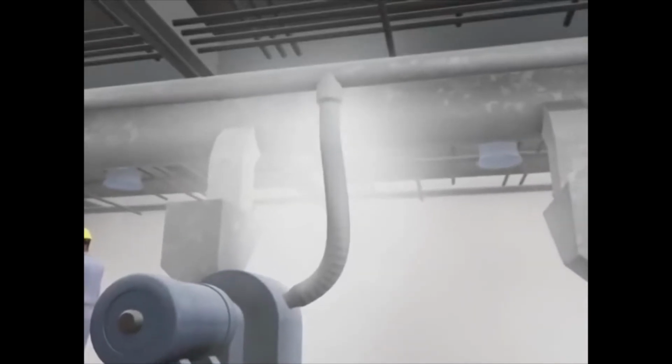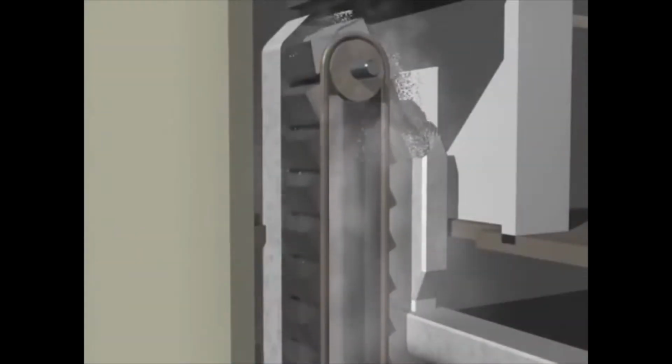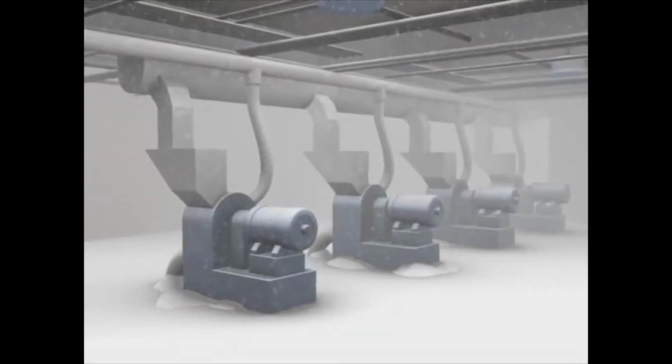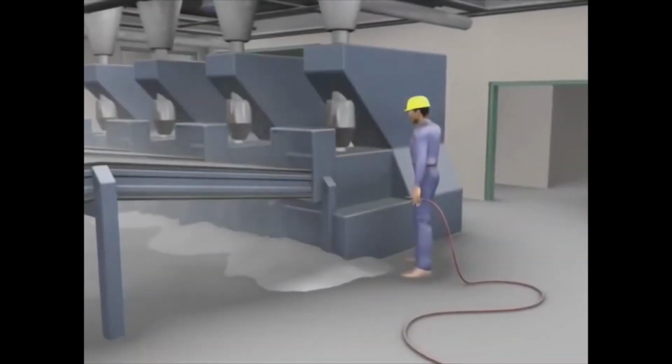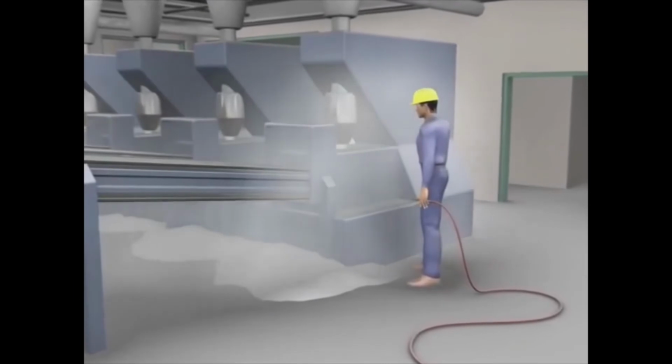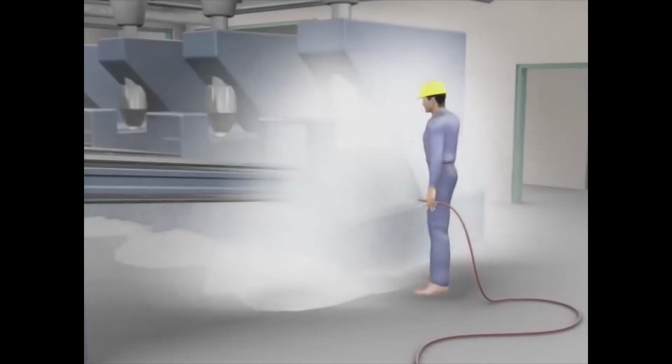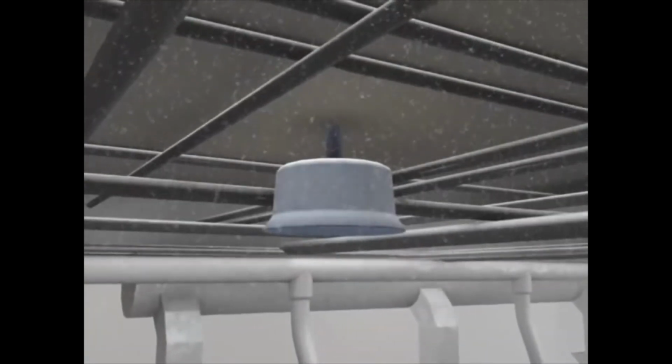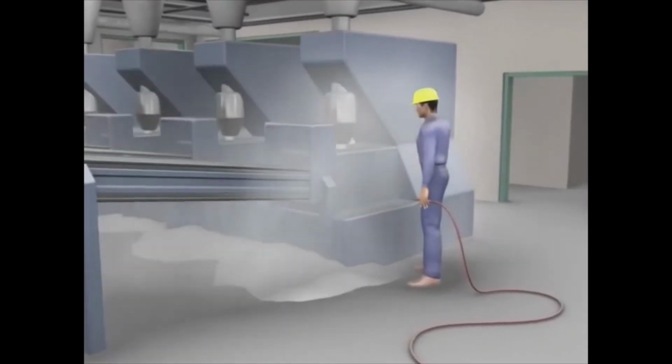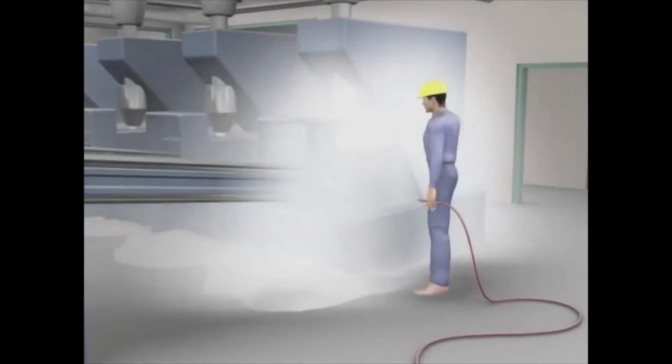The machines were connected to a dust collection system, but it was undersized and in disrepair, and it was not connected to the bucket elevators and conveyors. Significant amounts of sugar dust escaped into the work areas. Workers routinely used compressed air to clean packaging machines, further dispersing sugar dust throughout the buildings. Over time, large amounts of dust accumulated on elevated, hard-to-clean surfaces, such as ducts, beams, and light fixtures. These surfaces were not cleaned often enough to always keep the dust below hazardous levels.